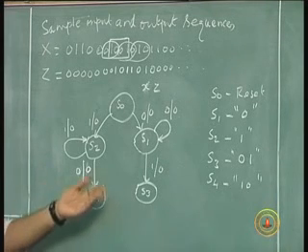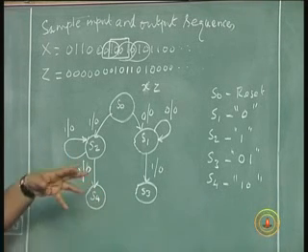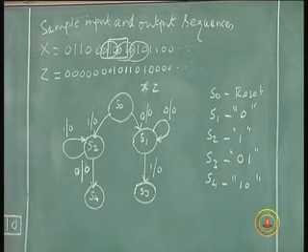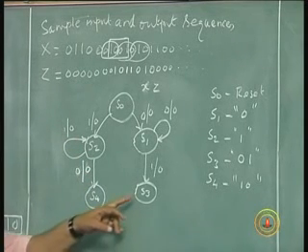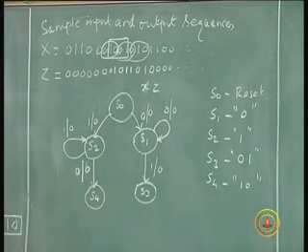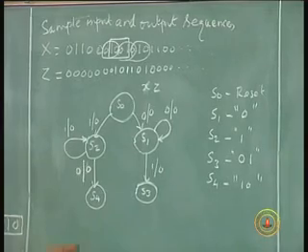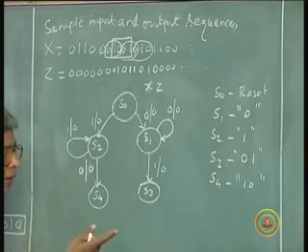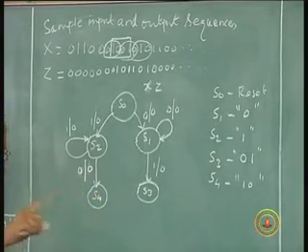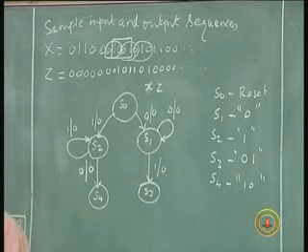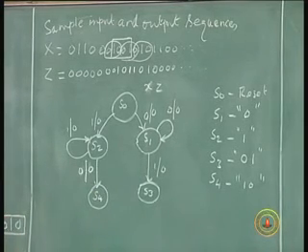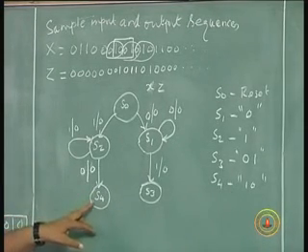So you have to proceed like this for each state, until you have finished your patterns and no more possibility is there. So in S3, 0, 1, if a 0 occurs, the 0, 1, 0 pattern is completed, and that could be also part of 1, 0. 0, 1, 0 could be the first 2 bits of a 1, 0, 0, 1 pattern, which is already here, S4.